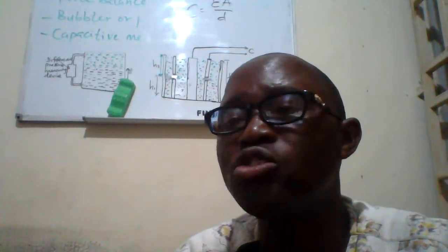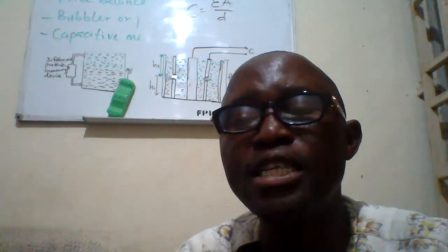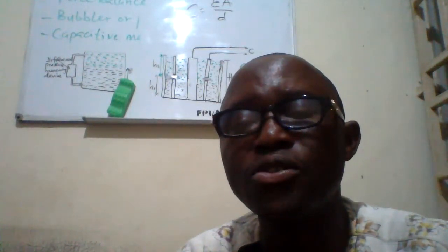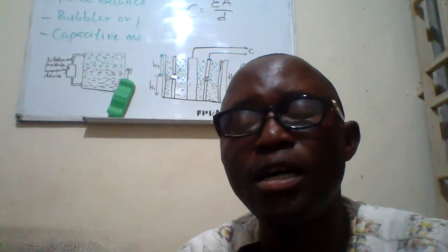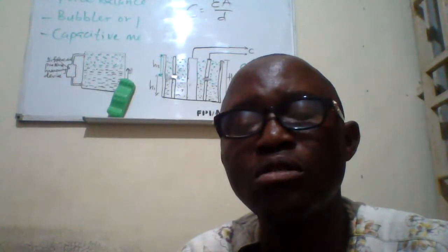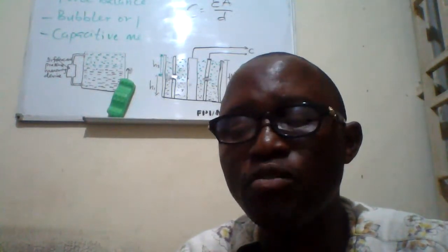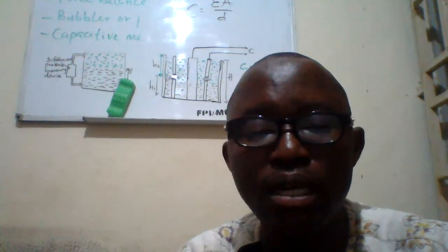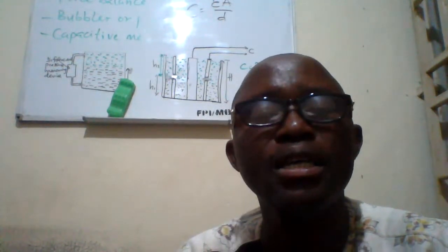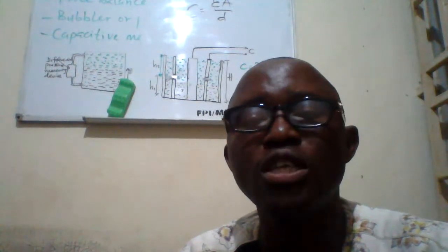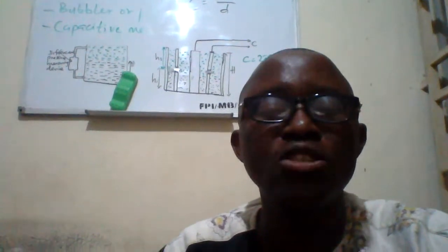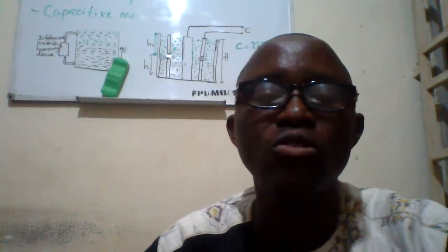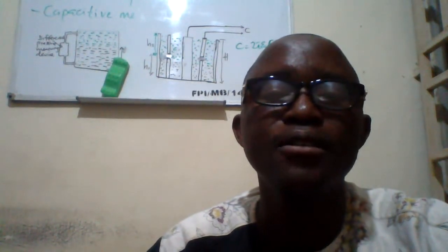Again, we also have another dimension in the formula, which is actually the radius. We have two values of radius, R1 and R2. The two of them also determine the calculation in the formula. So when you check that, you now see that the determination of that capacitance will help us to know what actually is the value of the height of the liquid in the tank. All right.